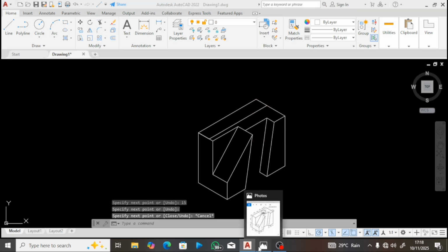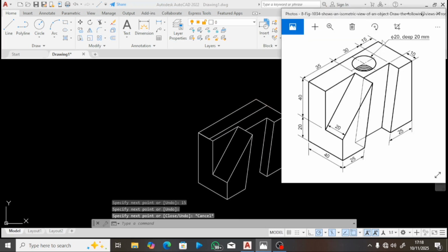Now, we have gotten the midline here. So we need to get another line that will cross this line to get the exact midpoint. So to do that, I will need to know the distance from here to here. So the distance from here to here is 15, and from here to here it will be another 15. That will be 30, because from here to here is 30. So I will need to come 30 like this to get the middle.